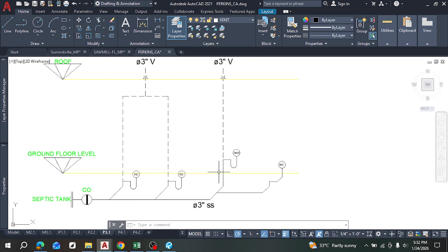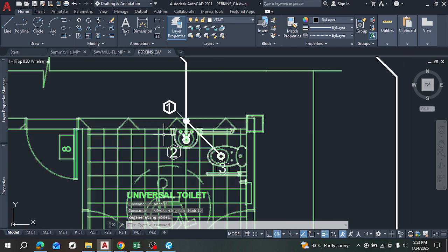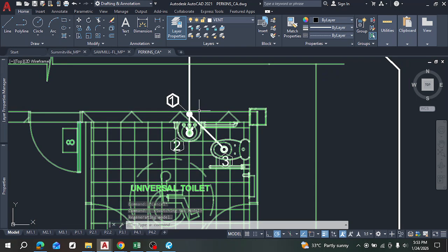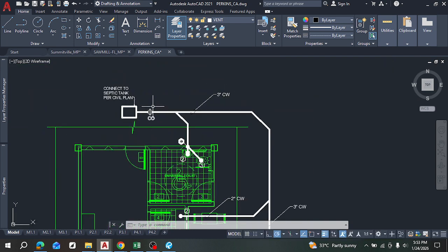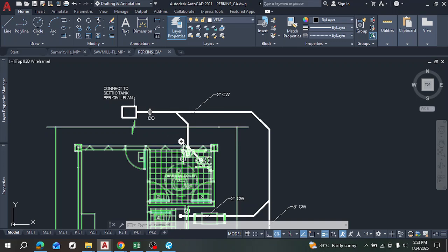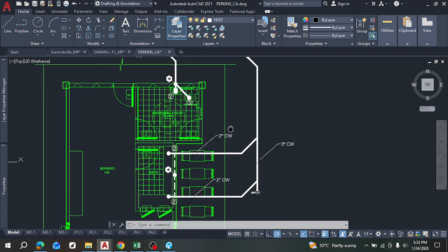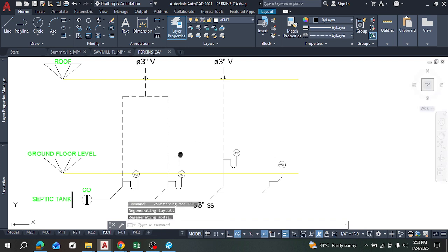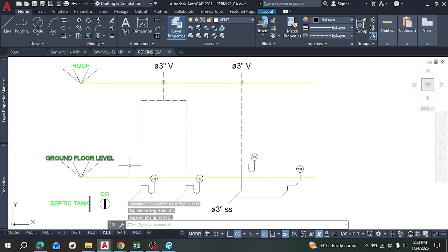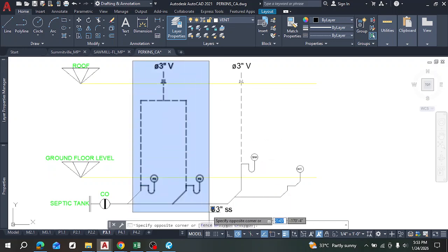So yes, then it also collects from. So also observe how this is the final. There seems to have been a mistake somewhere, right? Because this is the exit point. So what is exiting first is this WC and sink and lavatory rather than the floor drain. So that's a mistake on my part, right? These should be first, closest to this before this. So that's a mistake on my part, right?